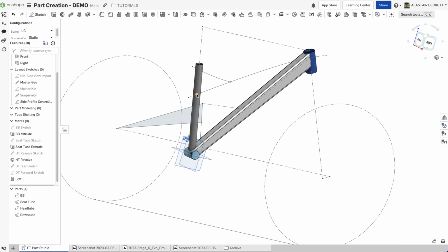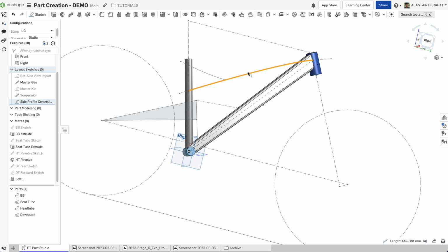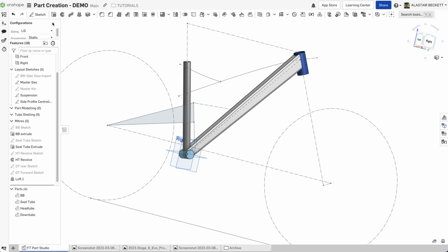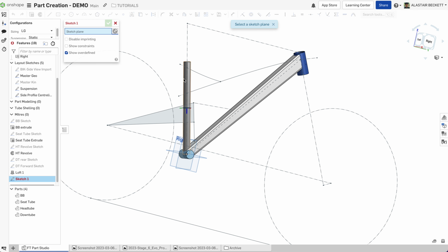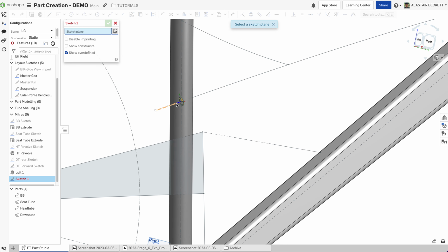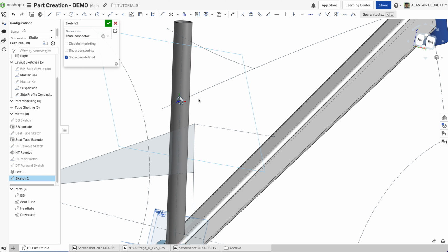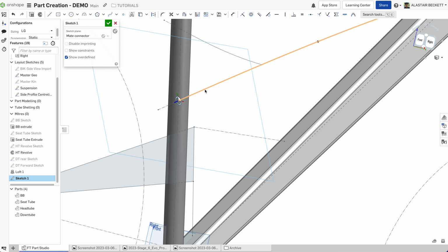We're going to loft it again, but what we're going to use is a bit of a guide or a path, which is this curved spline as well. So we follow the same principles. We'll have a starting sketch, and this is where this little construction line comes in. It makes it really easy to pick the starting point here, and make sure that it's kind of tangent with the spline curve.